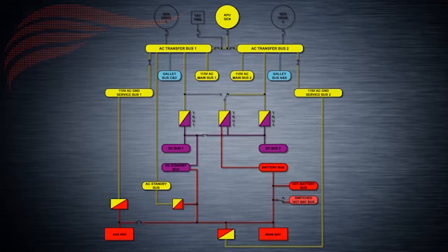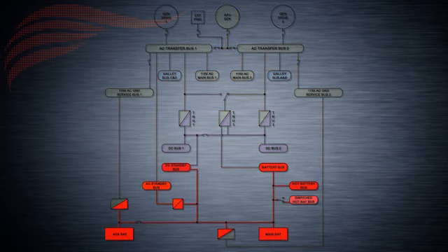The standby power system has two modes of operation, normal and alternate. During normal operation, different power sources are provided in case of partial power loss. A complete transfer to battery power is provided if all normal power sources were lost. As we mentioned earlier, the AC standby bus is powered by the AC transfer bus 1. The DC standby bus is powered by 3 transformer rectifiers. The battery is powered by TR3, and the hot battery bus is powered by the battery chargers.